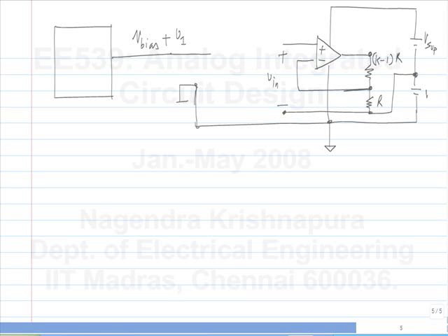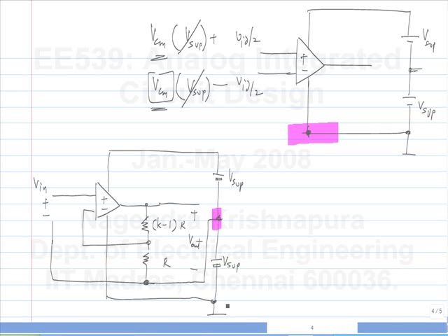So we had some supply voltages. So you're saying you remove this from this point? No, but then I have changed the performance of the op amp, right? Because before the swing limit was something, now it may be different. See, if I go back here, when I had the ground at this point, the op amp could swing all the way to V sub and to minus V sub, approximately. So now if I change the value of the supply, I will change the swing limit. Let's say I don't want to do that.